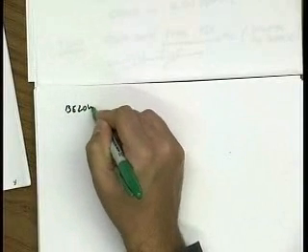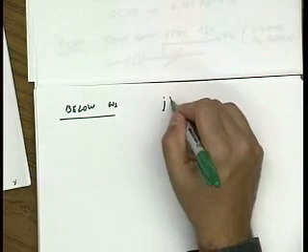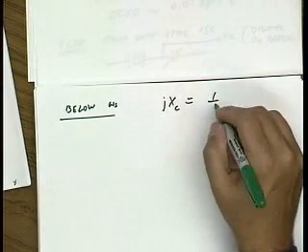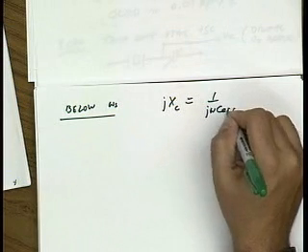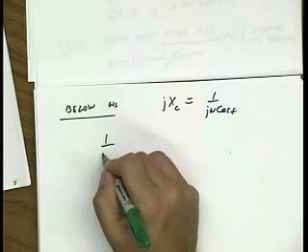All right, so let's look at a little bit more detail what the equivalent circuit looks like at different frequency ranges. So clearly below omega s, the series resonance frequency, our crystal just looks like a capacitor. So what's the value of the capacitance?